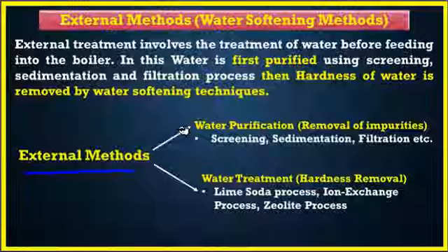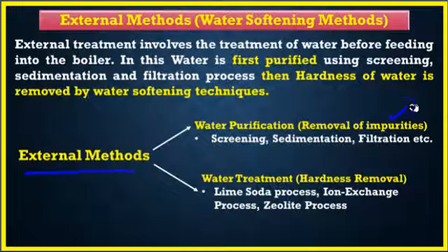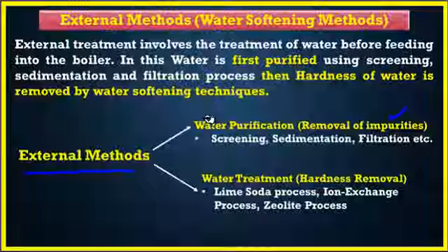First is the water purification, which involves the removal of various types of impurities, which includes removal of suspended particles, fine suspended particles, colloidal impurities and large impurities by screening, sedimentation, coagulation and filtration methods. For the details of water purification techniques, you can watch the video specifically made for the water purification techniques. The link of the video is given in the description box.